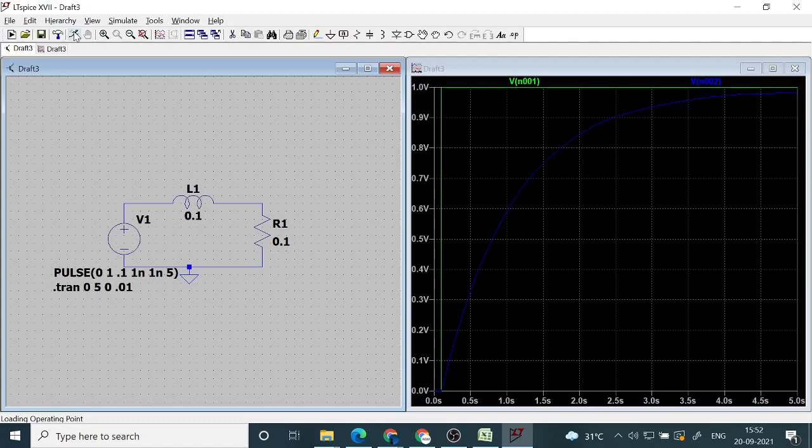In the last experiment, the voltage on the capacitor was rising at a speed which is determined by the product. So if the product of R and C was larger, it takes larger time. If it was smaller, it used to take lesser time. But here when you make it smaller, it takes larger time. Okay, so making things smaller, here making things slower. So that is one thing.